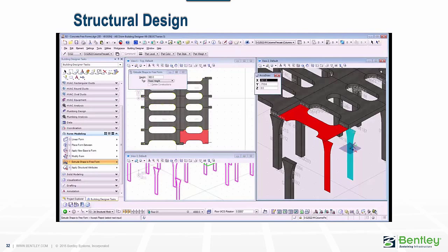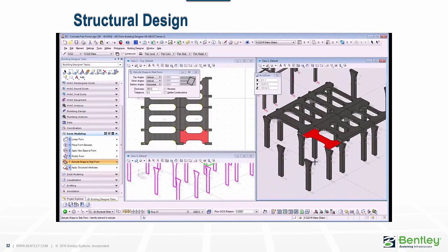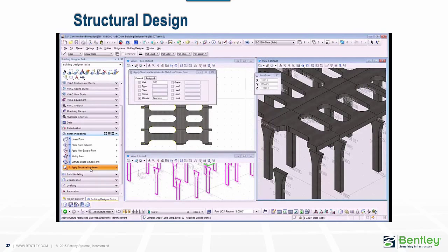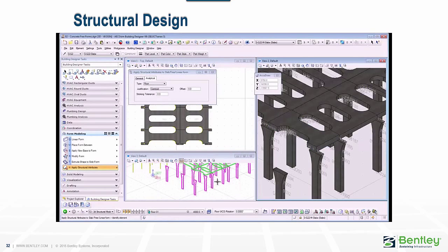You can even create your own custom structural elements based on some custom shapes. The software allows you to extrude custom shapes into solids and then apply the catalog properties and path information to that solid. This way, the solid gets converted into a BIM element like a slab or a roof and can be accounted for in the schedules and quantity takeoffs.